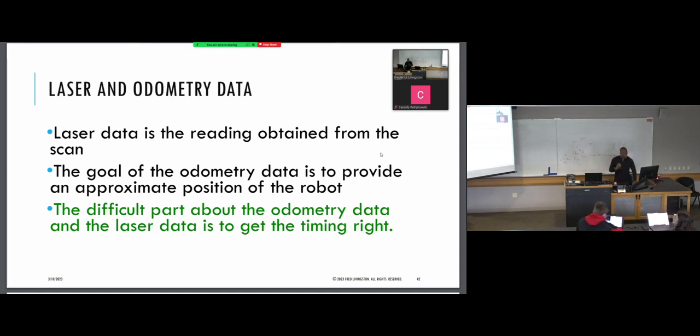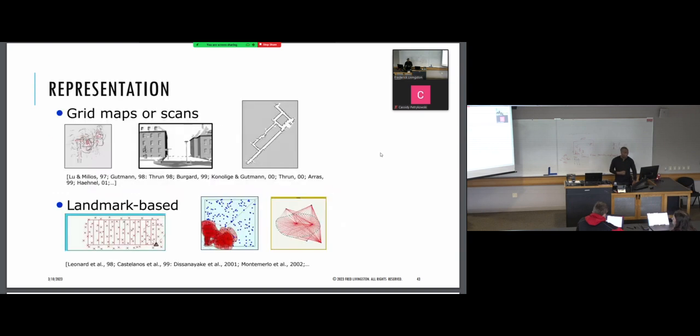But these algorithms are already going to be able to do that for you. And there's grid-based SLAM, where I take my map and divide it into grids. So I'm not using the points here, and I could make these grids larger or smaller.